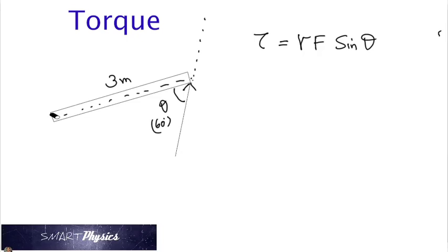So in this case, it's the actual angle that I've given. But you got to be careful. I might give you the other angle, you know what I mean? And then you should know, hey, it's the angle between the radius and the line of action of the force. Take that angle. That's a simple thing to remember, isn't it?